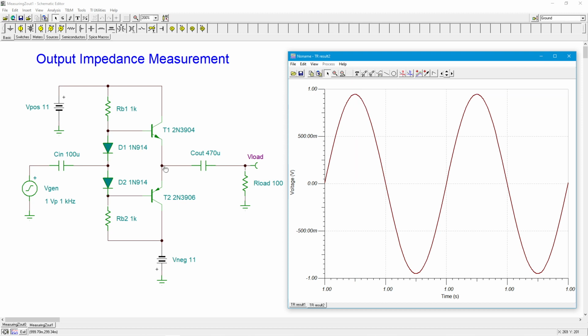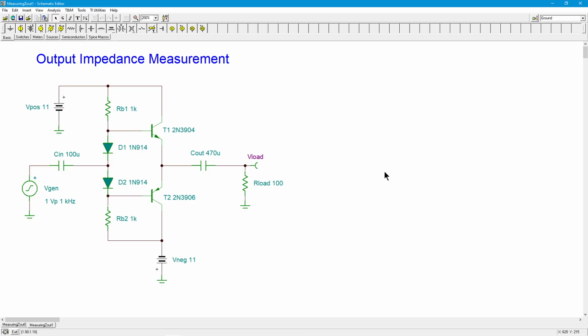So that little bit indicates that the internal impedance, the Z out here, is where we're losing a little bit of that signal. Now, sometimes in a general case, usually not with a power amplifier, I should retract that, they'll do a matched impedance thing. They'll put a potentiometer out here or resistance decade box, and they have you adjust this until your V load falls to half of your unloaded. And when that happens, you have the matched resistance case, which is what I showed you initially, with the 200s. So when that happens, you know that whatever your load is, that's your Z out.